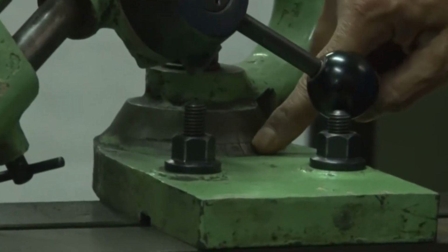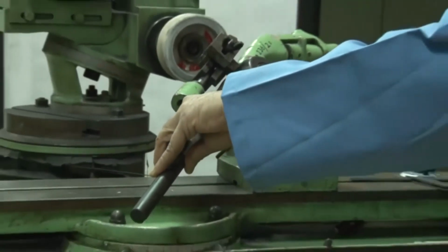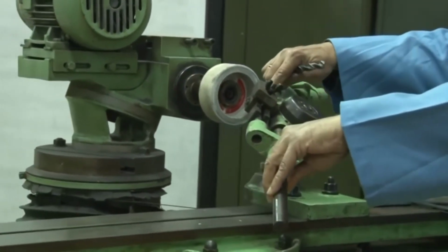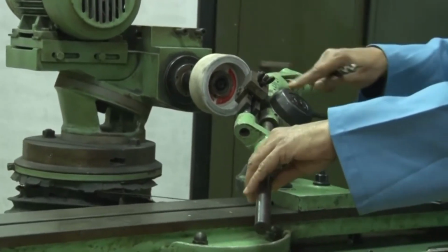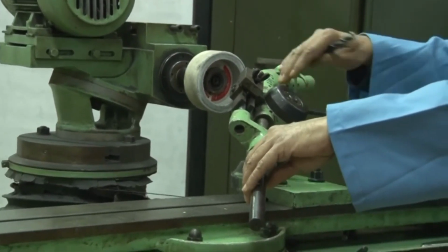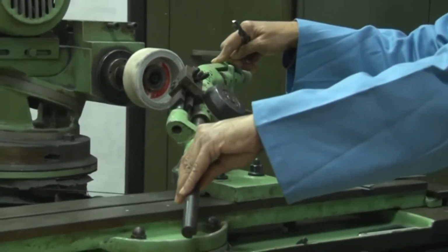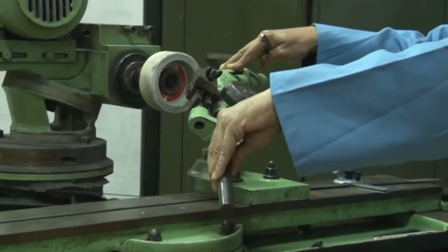Now, at this angle we have to set this attachment, and here there is a scale, the scale is graduated. We have set it at an angle of 118 degrees, meaning that if we now move this in this way, the face will be in touch with the grinding wheel, because it is set at 90 plus 28, so it is 118 degrees, and in that case it will be ground like this.